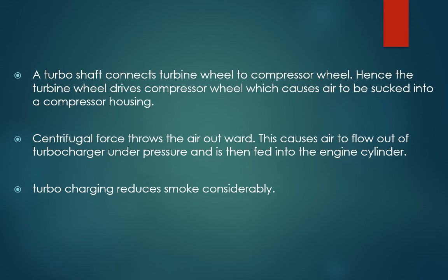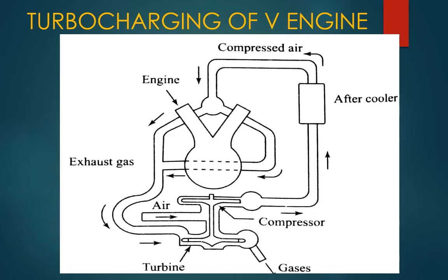The centrifugal force throws the air outward. This causes the air to flow out of the turbocharger at a higher pressure, right? The turbocharger reduces the smoke of the engine considerably, right? This is what it is.